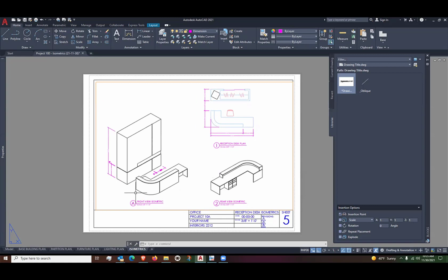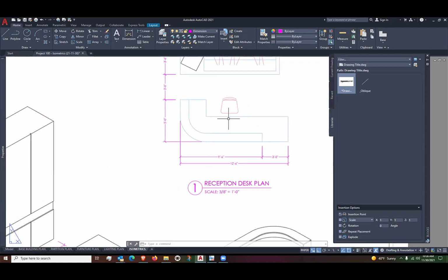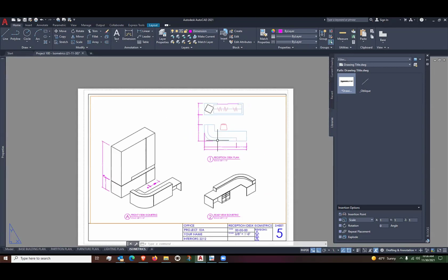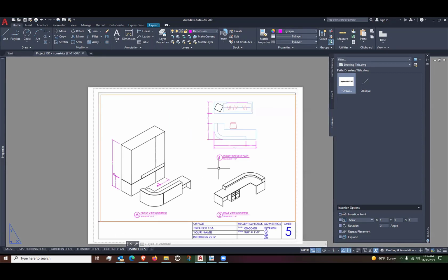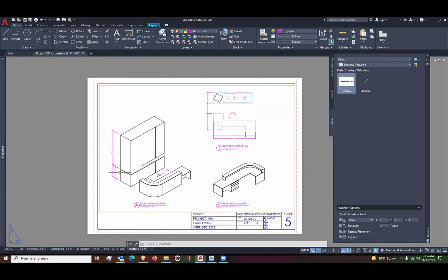And the reason you don't do it is a lot of times you make changes to the design. And if I make changes here, I have to change those dimensions, and then I have to remember to make those same dimension changes over here. So try to find unique dimensions that are relevant to each of these that will convey to the contractor the design intent here.